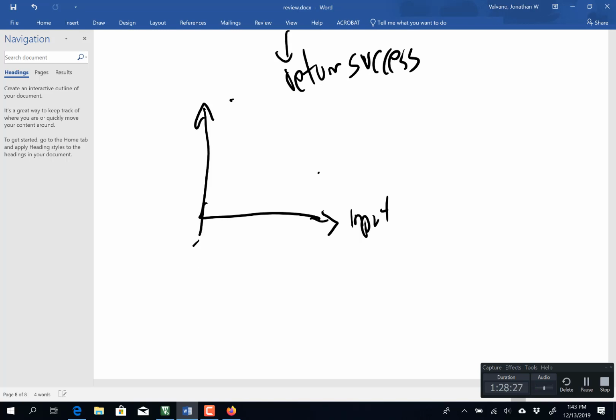Analog, 0 to 3 volts. Okay? So what's the output? Digital. It's 12 bits, 0 to 4095. Okay. What's the relationship? Linear. Now, if you zoom way in, it's stepped. But if I zoom out at this range, it looks like a straight line.